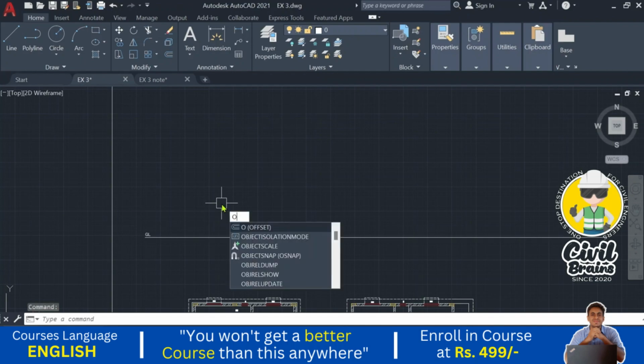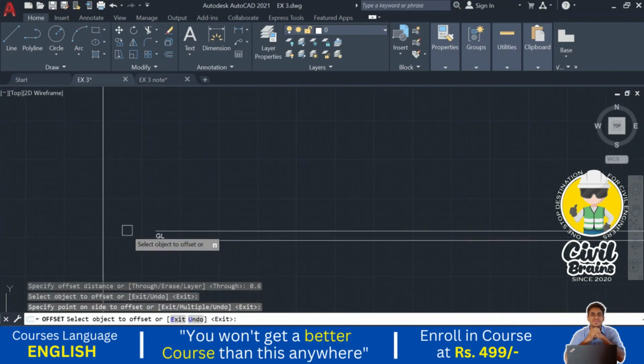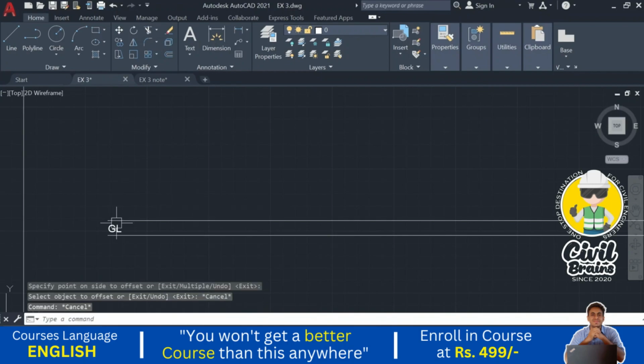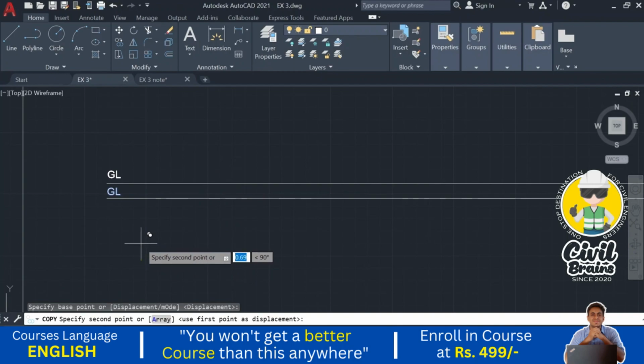I just use the offset command, offset, press enter. What is the level? Ground level to the plinth level. Level is 0.6 meter. Press enter. Okay, so this is our plinth level. If you want, I will write it here so we will not get confused.